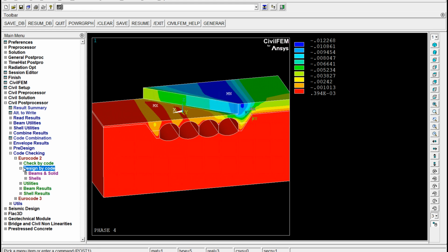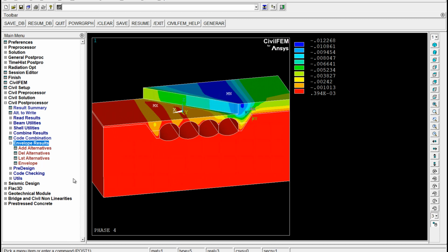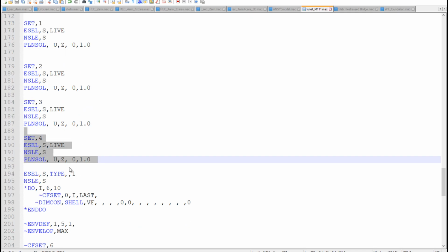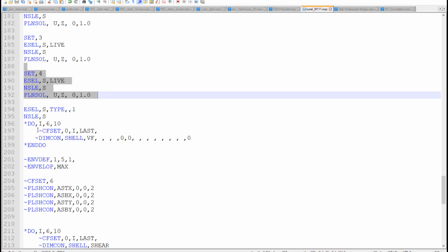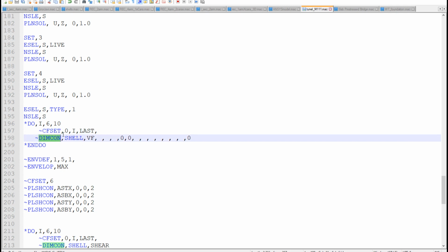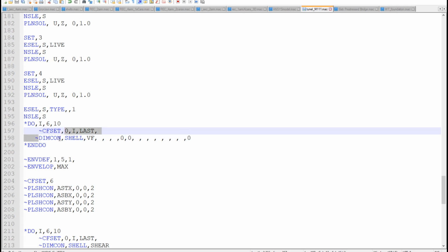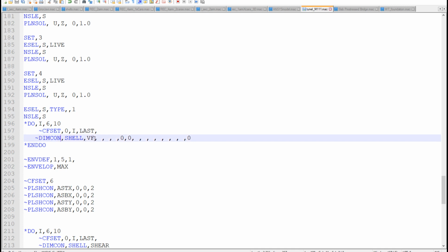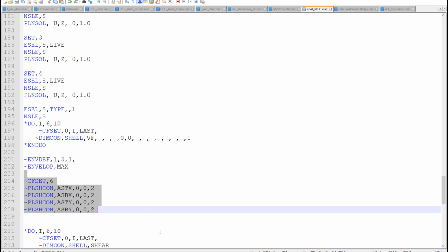After designing the 5 load steps, we create an envelope of those results. We can do it by commands in a very easy way. We are reading the load steps, and with this command, dimension of concrete, designing of concrete, the cells, we calculate reinforcement amount, and finally we calculate an envelope. So if we read that envelope, we can plot the results.